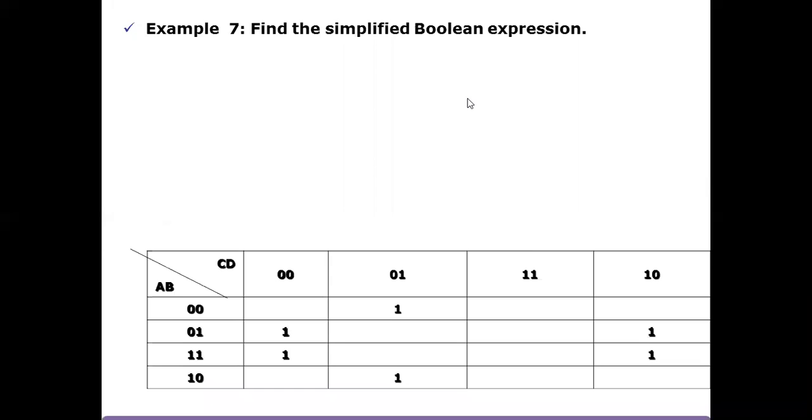And there's another problem where the function is not given for the simplification. And you can see here, there are some values given. So try to do the grouping, and keep in mind you can make these as cylinders in both ways. Think of vertical cylinders and horizontal cylinders, and come up with the solution which has fewer groups, which are large, and it could be overlapping.